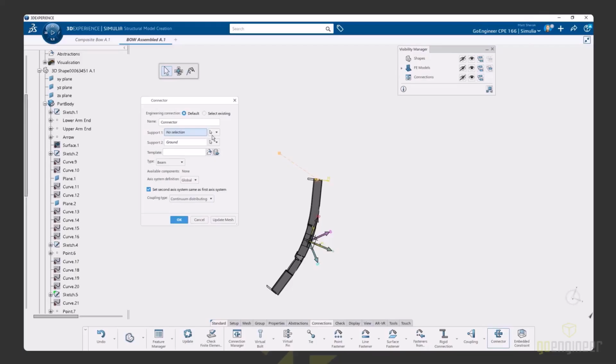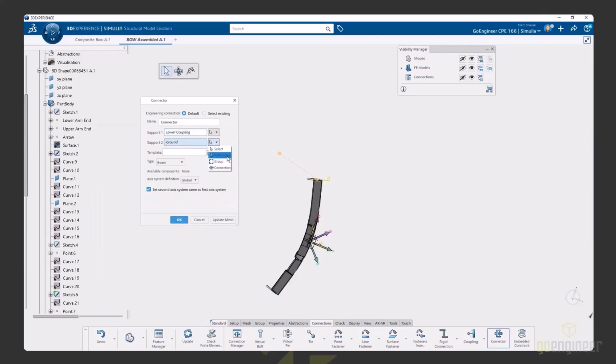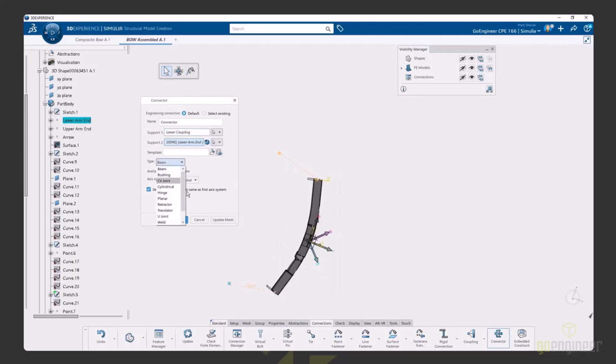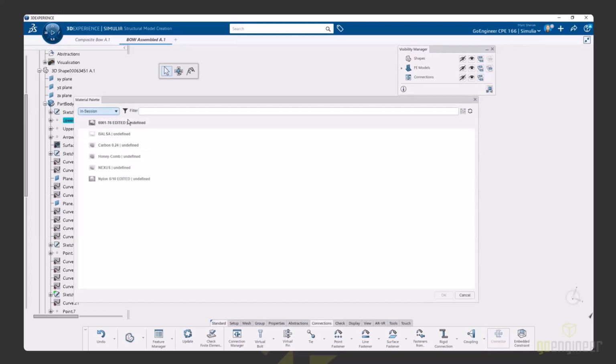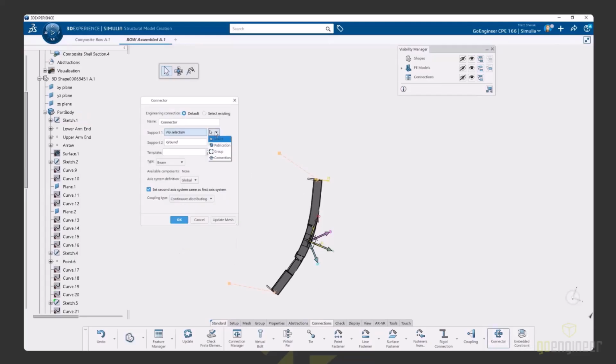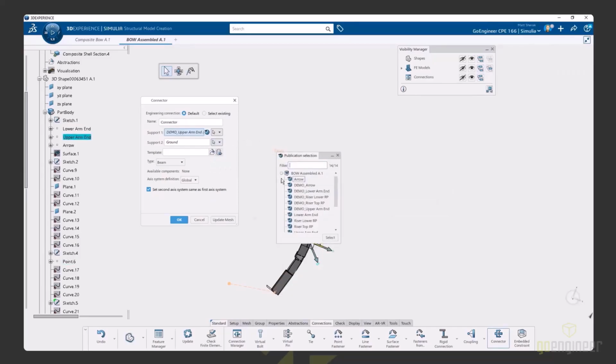So I'm just going to go through and create both of the arms of this bow using these connector elements and using the reference points that I've created with CATIA here to simulate this structure as a whole. So we're going through, it's going to be the same 10 millimeter radius on the bottom half of this. Again, we're going to go with a 6061 T6 and linear, click OK. And now I can go ahead and build the string as well. And this is done the same way, right? We're just grabbing the two ends of wherever this string happens to be.